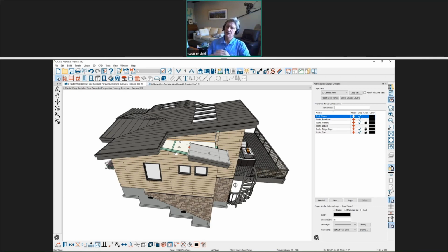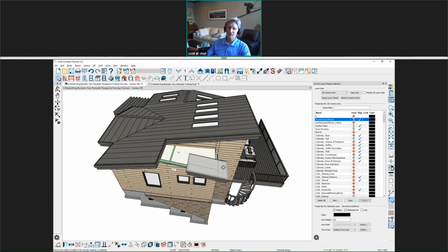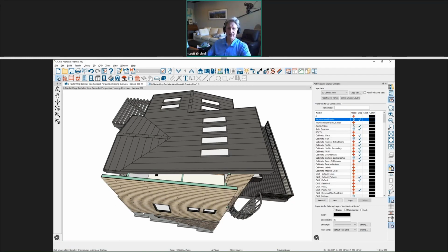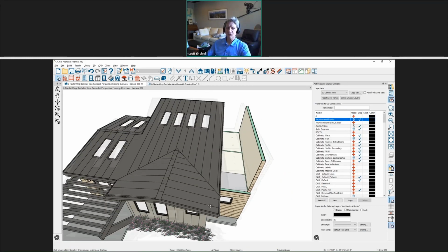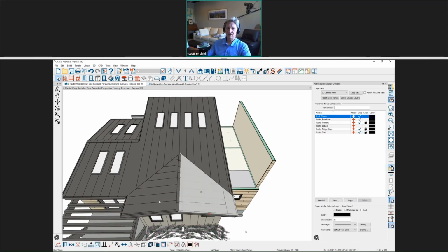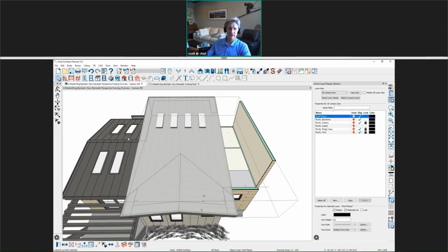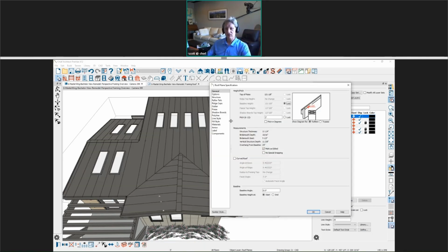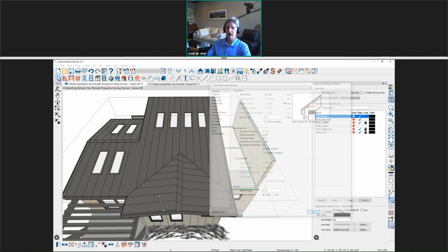You can also build a new roof plane and lock the other roof plane. So if you have an as-built condition, let's suppose that I don't have any roof planes over here, and we just delete them, and that gets rid of that gable wall. These roof planes can be locked, so if we open them up and check, right now these are marked as edited, so we know that they have been touched.